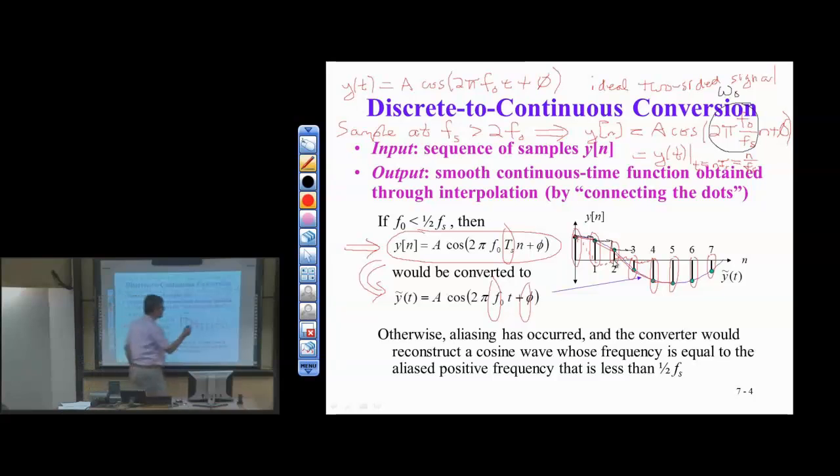Okay, so the ideal low-pass filter is this rectangular pulse. Here's the ideal low-pass filter. It's a nice rectangular pulse. The impulse response for this filter would be a two-sided sinc. Can't build this in practice, but it's nice to know that it exists in the ideal world somewhere. So the sinc is kind of the nice shape we'd like to do. So what can we do in practice?